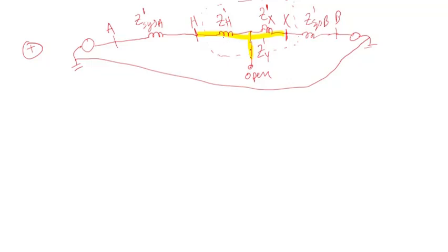The way you would calculate the positive sequence impedances of the T model is to apply something like the short circuit impedance of the transformer. You apply voltage to one side, like the high voltage, short the low voltage side, and leave the Y side open. That gives you the impedance from high to low.